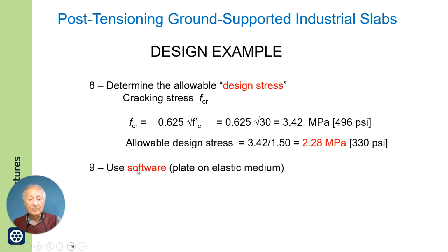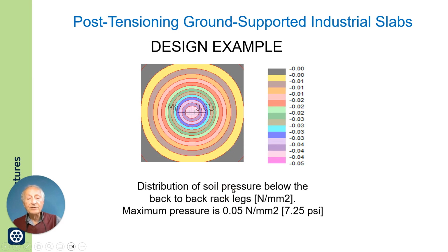Then we use a software which is based on plate on elastic medium. Define the design parameters and we obtain solution. Solution typically gives you a contour of soil pressure and gives you a contour of bending moment and so on. Here is a contour of soil pressure. I have shown it for interest.